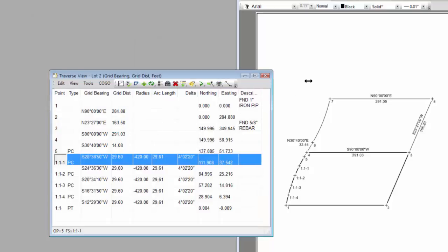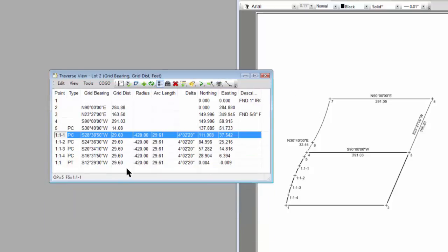Close it. So do you see how the points are part of the survey now, the points I inserted between the PC and the PT, and they're also on the drawing now. And that's really the advantage of having Traverse PC do the line work for me. So as I work with a traverse as part of a survey and develop the points and the line work in there, those show up for me automatically in the drawing. And in fact, these lines here get all their data from the survey points to begin with. In this case, even the curve data that's involved there.